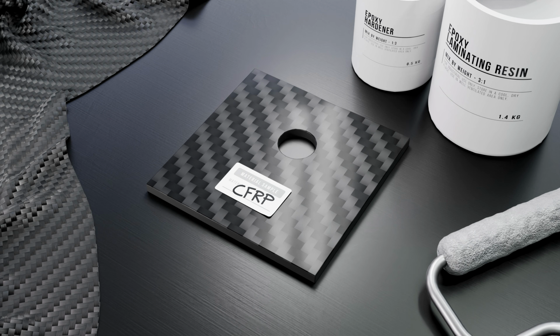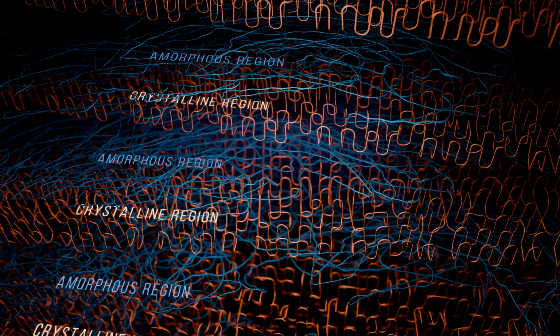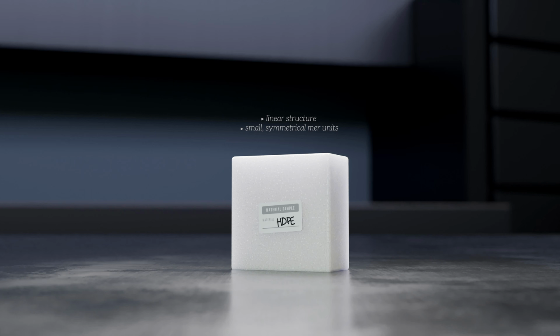Unlike metals that have a very regular crystalline structure, most polymers are semi-crystalline, meaning they contain both amorphous regions, where the polymer chains are randomly jumbled together, and crystalline regions, where they align in a very regular pattern that allows them to pack together very closely. These crystalline regions often form spherulites, spherical regions of highly ordered chains that grow outward from a central nucleation point when cooling from the melt. Linear polymers with small symmetric mers tend to have the highest degree of crystallinity because these characteristics allow chains to pack together very closely.